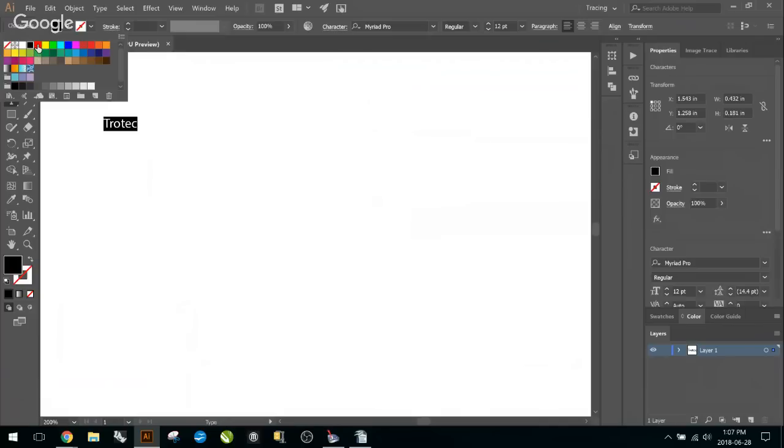Illustrator is sometimes tricky, depending on if you're dragging in a file or starting a new file. Maybe you didn't select the right options for your document. This might show up as CMYK. So you're going to want to change your colors to RGB colors. To do that, we'll show you here.